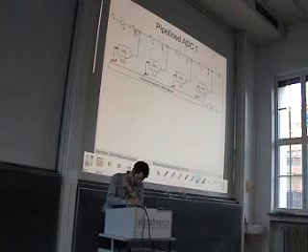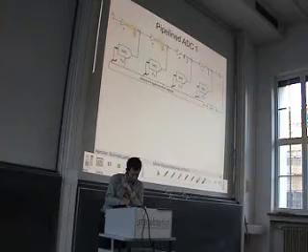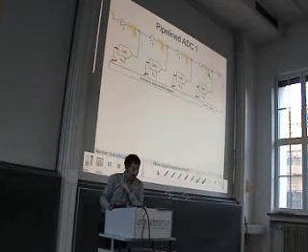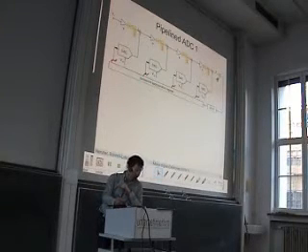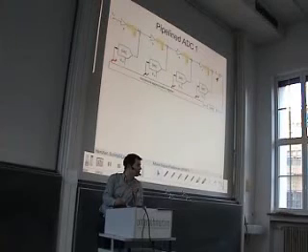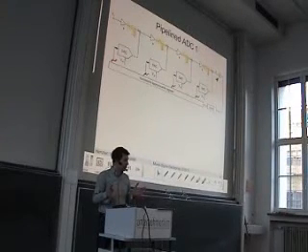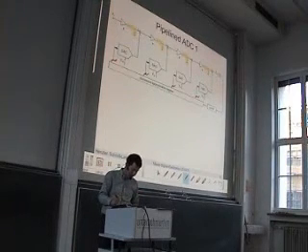So what we did so far is to sample at the input, but now we also have to sample after each stage. And what is missing so far is that we cannot use this comparator for all of these stages, because now all stages work simultaneously. So we need a comparator in each stage.